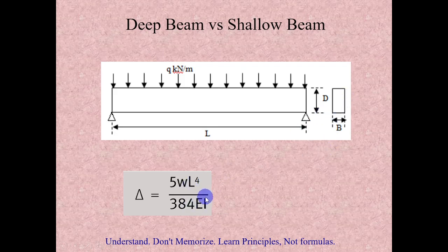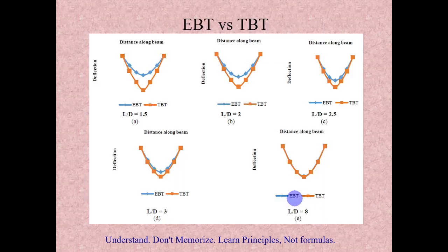In addition to this, there will be one additional component, which is the deformation due to shear force. Usually we neglect this. Basically this will be very small in the case of a shallow beam, but in the case of a deep beam this shear component will be high. So we cannot simply neglect this and proceed. That we will see by the results.